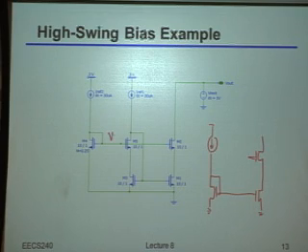Okay, so let's just call this VB here. So I could have indeed just connected that VB to the cascode device over there, and then said, okay, this is the point at which I'm taking my output current. So maybe I won't draw a current source here. I'll just say that's my output current right there. Okay. So the question I want to ask you guys is, why do I claim that what I did in the real slide here, in other words, what's drawn in that Cadence schematic, is probably a much better way of doing things in terms of just the current mirror itself versus what I drew on the right?